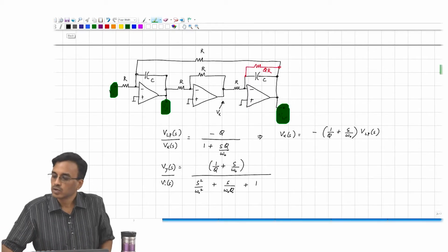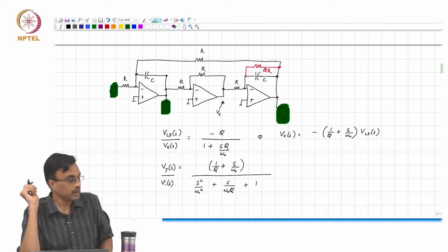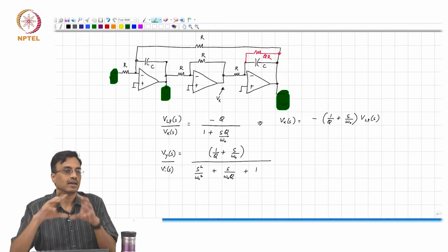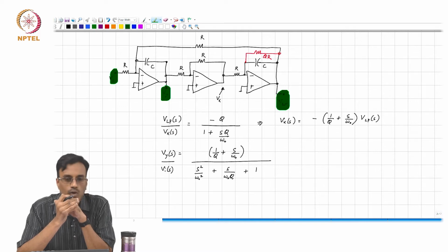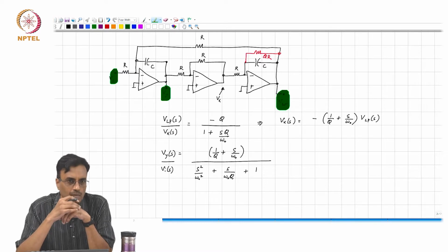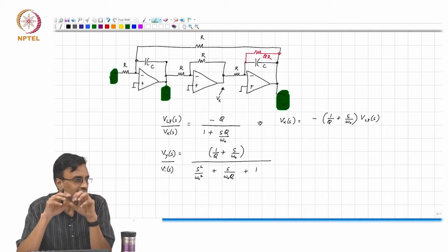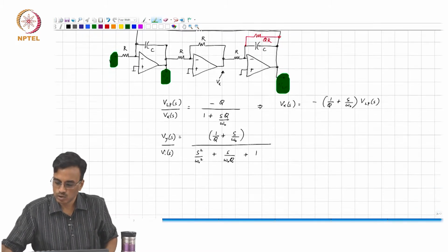All right. So, basically that is all I had to say about the second order biquad. Now, let us see the issues that crop up when you cascade a bunch of biquads. After all, we are interested in realizing a high order transfer function. And therefore, as we discussed, what we are going to do is split up the transfer function into products of first and second order sections, and then just put them in cascade, all right. And it's easiest to work with an example.